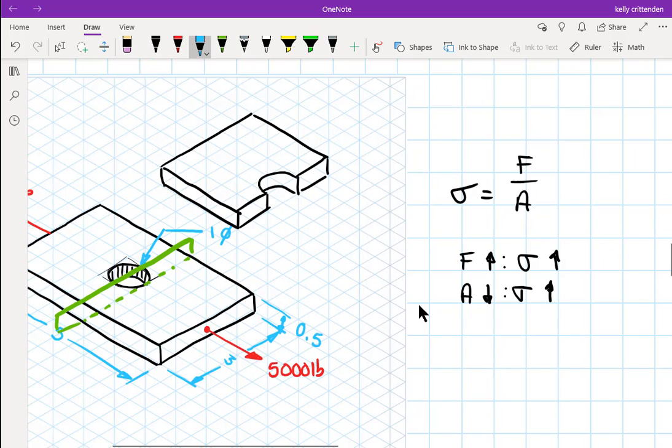And that's my cut. If it broke really cleanly, and when I'm calculating these stresses, I'm assuming that everything snaps perfectly in half on these planes. In real life, they're all jagged. We're not in this class worried about the roughness of stuff. We're assuming everything's perfect. So these little shaded areas, those are the areas that support my load. Let's make it red. I've got 5,000 pounds of external force. And then I'm going to assume that half of it ends up on either one of these little surfaces around the hole. So 2,500 pounds gets split up there, and 2,500 pounds on that side.